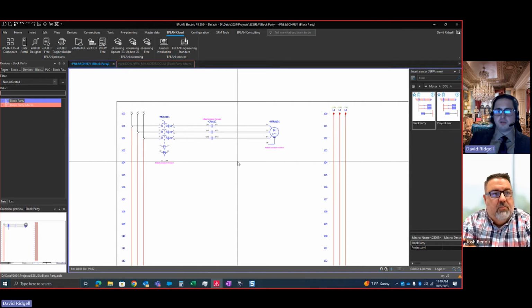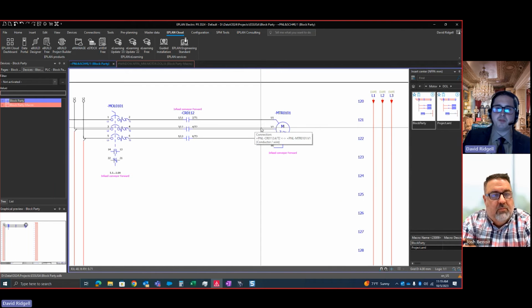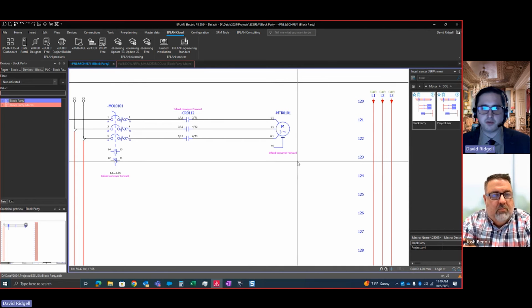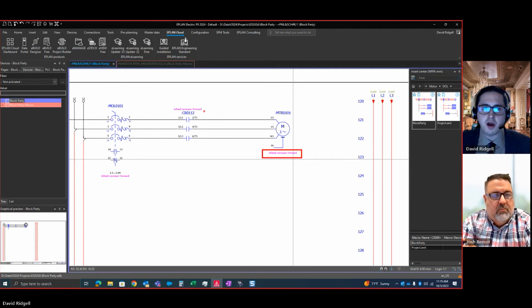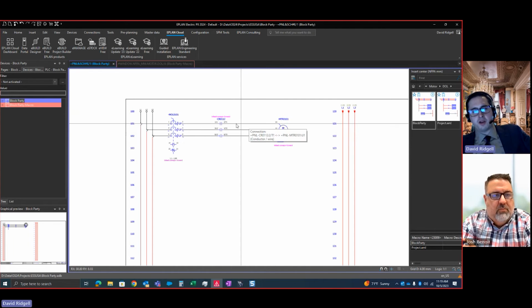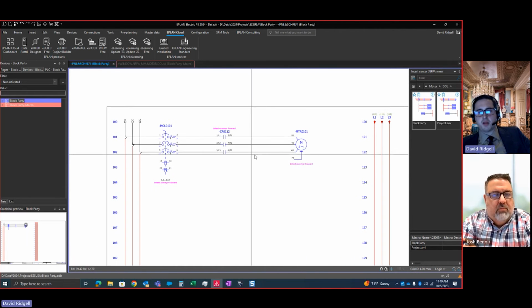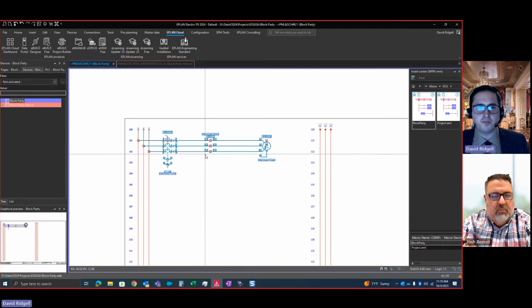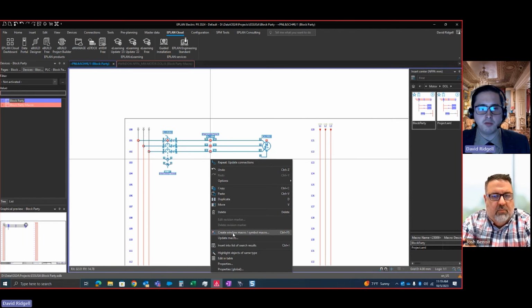I was like, it would be helpful to have one common text for the entire circuit. So rather than typing this 3 times, I use a block property in this macro, and then I create the macro, and every time I place it, I'm only changing it 1 time and everything changes. For example, let's say I copy all of this to make a macro.